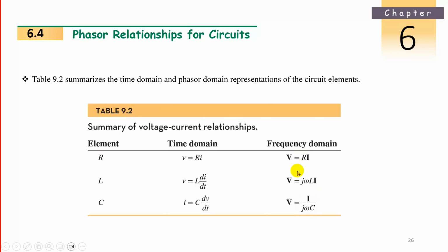So we can relate for DC. When DC is there, what is the frequency? Good, very good point. Frequency is 0 for DC. And I told in DC, inductance will behave like as dash. Short circuit or open circuit? Good. Short circuit. It will behave as a short circuit. Capacitance will behave as open circuit because its two plates are there. In between, nothing will come.